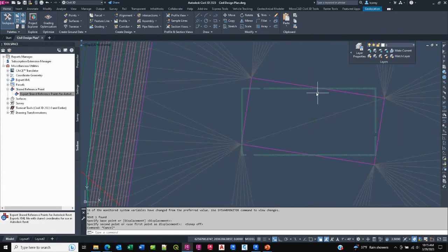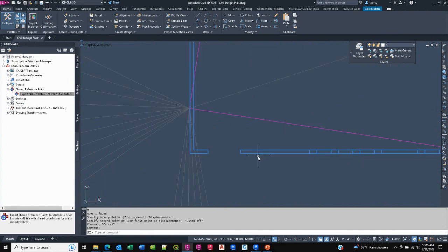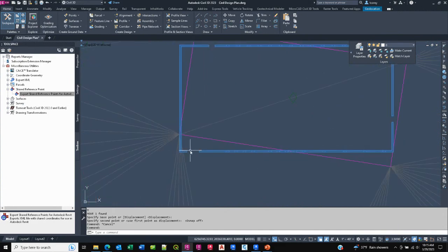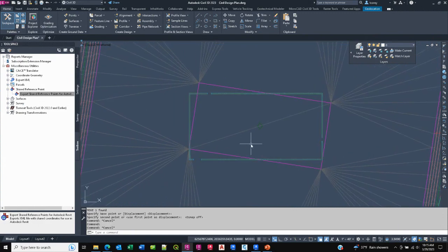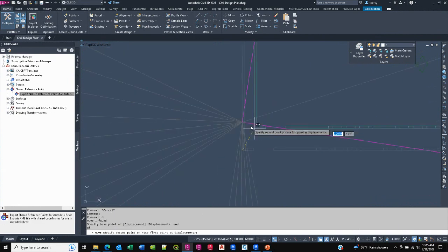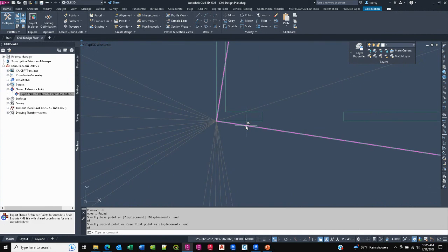Now, if I want to clean up this drawing, I can do that. I could explode that down into line work and clean it up so all I have are the exterior lines. Now in this case, I'm going to go ahead and keep it as it is. And what I'll do then is I'll take this and move it into place. I'm going to move, picking up at this end point and placing it at this end. Okay.